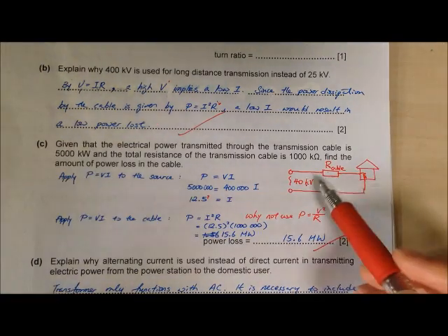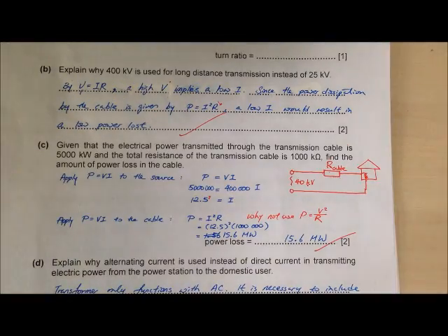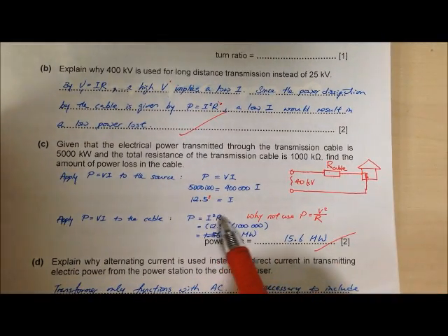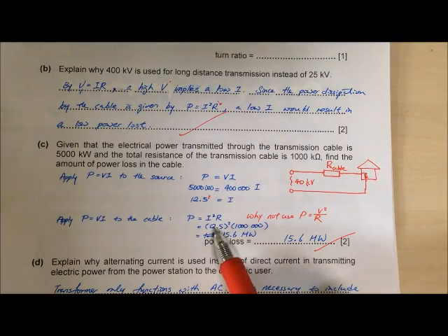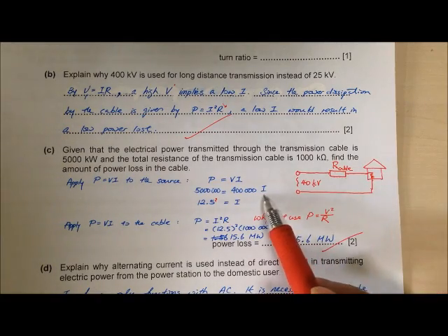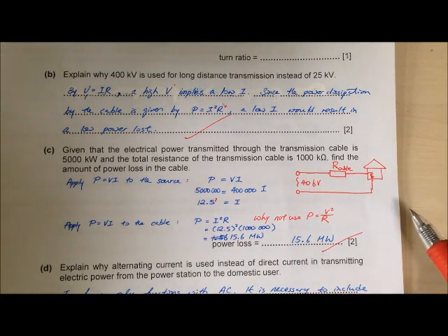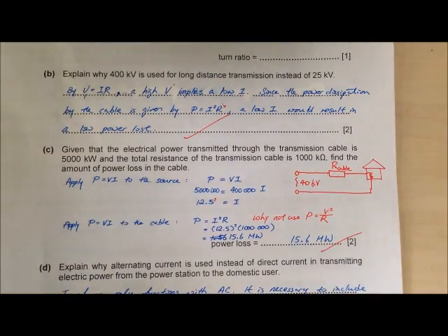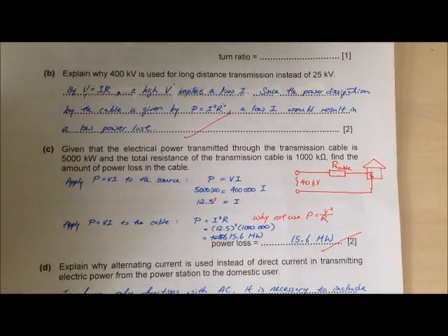So what you can use is that you know this is connected in series, so your current will always be the same. So that's why you have to use I squared R. And when you use I squared R, you realize that, okay, my I is not going to change regardless of this, because that's my supply, right? My supply gives that much current. So that's why here you get your 12.5 ampere. So just use your I squared R, you will get the power dissipation, and you find that it is really quite a lot. Okay.